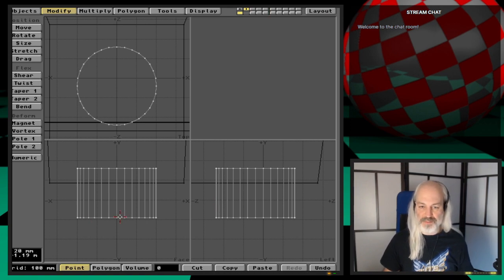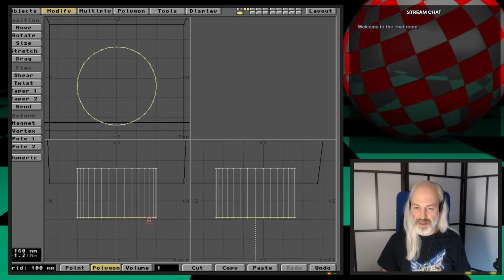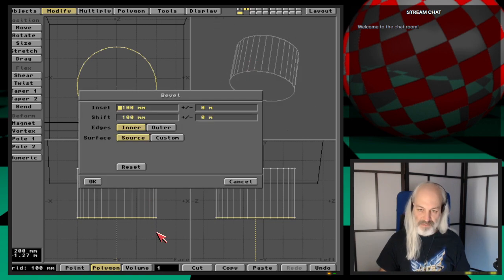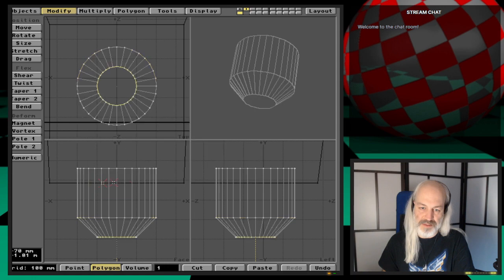Okay, back in the modeler, first let's start by smoothing this guy here. Bevel it, and let's do an inset. I have a grid of 100 millimeters by 100 millimeters. If I do that by default, that's what I will be getting, and that's not what I want.